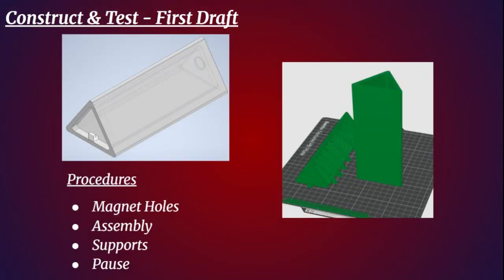Now that I had everything in check and all the prototypes had given me all the necessary dimensions for the final product, I updated all the models and added in holes for the planned magnets. Right before 3D printing, I grabbed the models I made for both pieces and made an assembly in Inventor. This assembly was to check if all the pieces fit correctly without any issue, as an extra precaution. After everything checked out, I began the 3D printing process. I set the 3D printer to use carbon fiber PLA to print out the draft of my design.